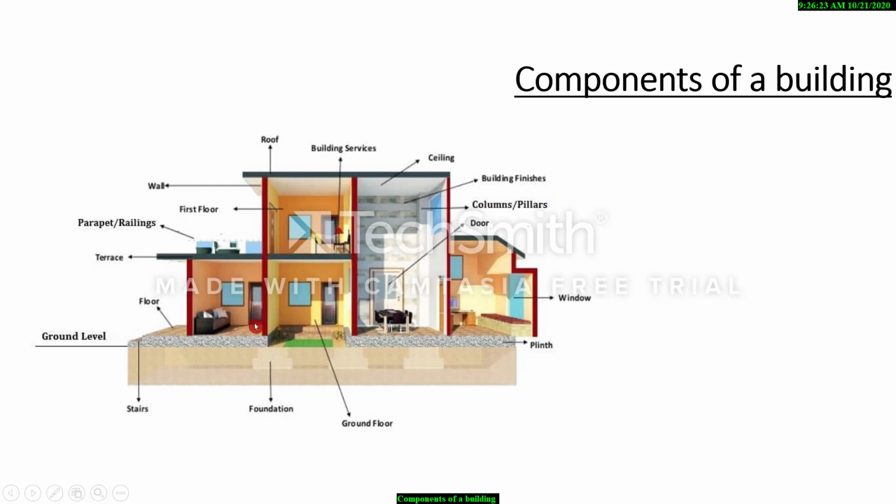So, the superstructure is a part of structure which lies above the plinth level. So you have the plinth here from the ground level. It's a raised platform. So above that, every structure belongs to the superstructure, and the construction between the ground level and the top level of the plinth is called the plinth structure. And every construction below the ground level is called a substructure or foundation.